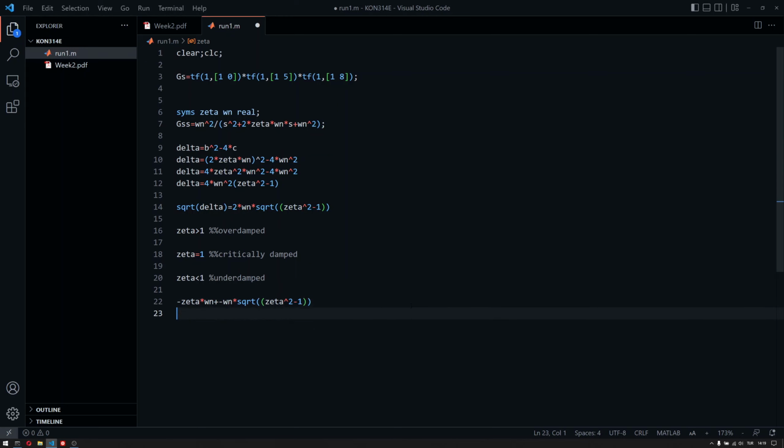Now this is also aligned with the fact that we can just use first order systems and say that 3.91 or 4 divided by the pole gives us the settling time. Since our system had real poles, we could just take the real part, which is p itself, and 4 divided by that gives us the settling time.